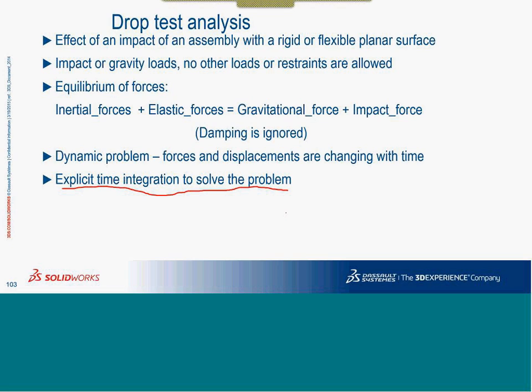You will also observe, even though I am saying it is faster, that typically when time or dynamics comes into the picture, it really takes more time to solve. And we always want such bodies to be simplified into shell elements or a simpler scenario. We might want to idealize such geometries into shells or beams, and both of these are not supported in drop test.